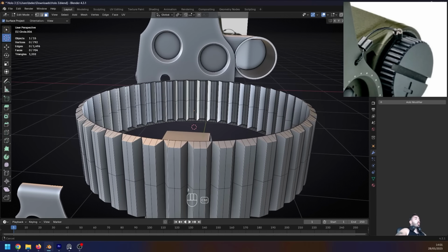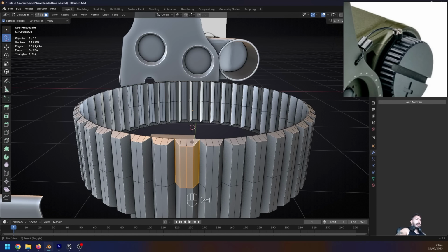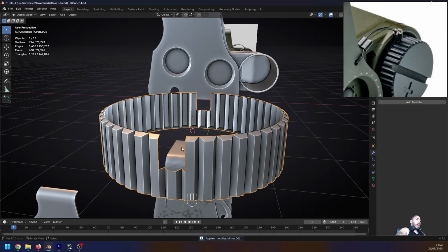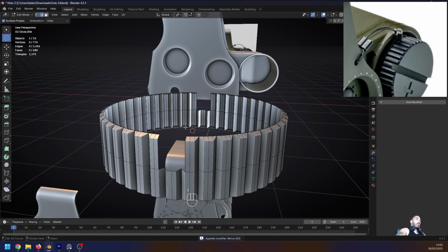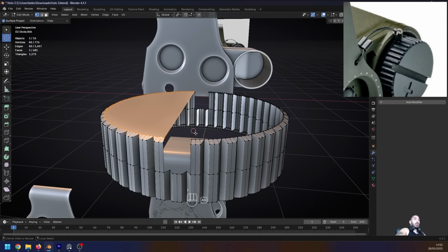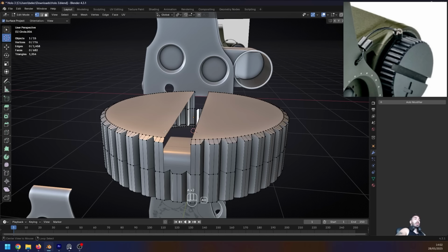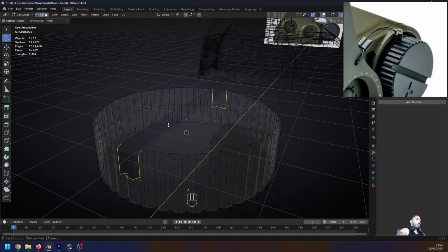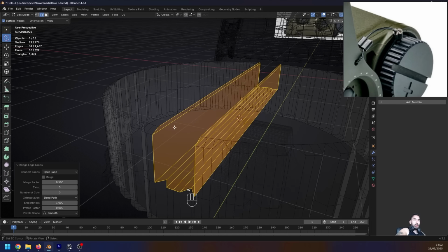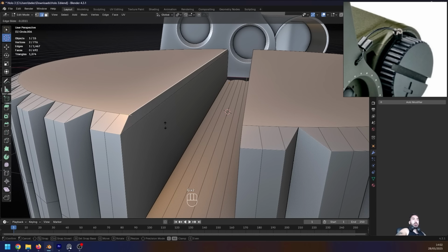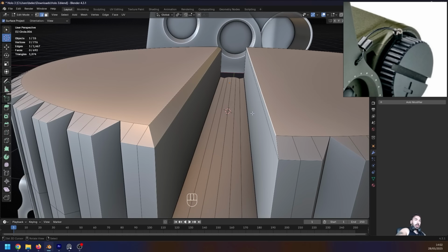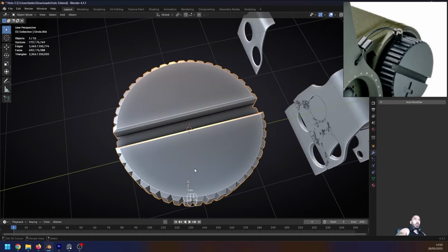and now we just have to cut out this gigantic gap in the middle. To create that gap, I'm first going to have to select this section over here, and I'm going to delete the faces there. And now once I created a gap here, now I just have to fill in all the stuff in between. So I'll take this face at the top, fill that, fill the other side. We can take this entire edge loop, deselect the 2 big edges at the top. I'm going to use W, bridge edge loops, and then I'm just going to take this edge, I'm going to slide it until I hit this next vertex. I'll also do that on the other side, and there you go, we got our gap.